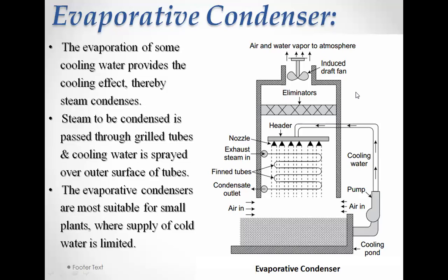So all these cold storages in our area make use of such evaporative condensers. We are going to visit one of these cold storages. I already discussed the plan with the HOD sir. And there you can see such condensers. Water is continuously dripping on those condensers and the cooling effect is produced.